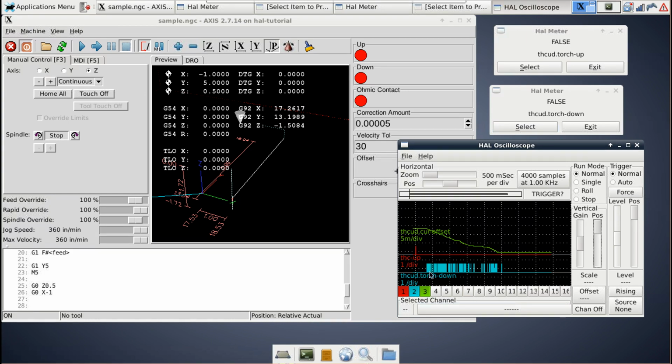So you can see here by how solid blue this is, that was actually the signal going up and then right back down immediately. And it wasn't continuously up, otherwise you'd see a solid step like that. But it's going up and down really, really fast because it's continually catching up and then stopping that signal, then waiting a moment and then saying, oh, I need to go down further, sending that as a quick series of pulses, kind of like Morse code in a telegram. And that's being translated then to a fairly even and downward slope on the current offset.